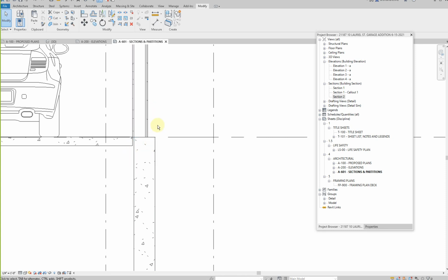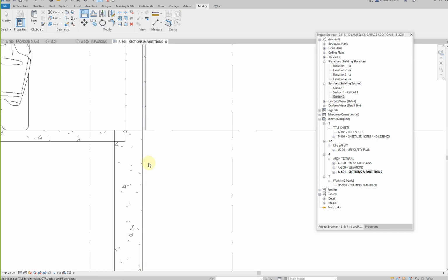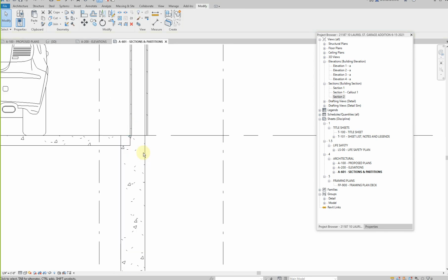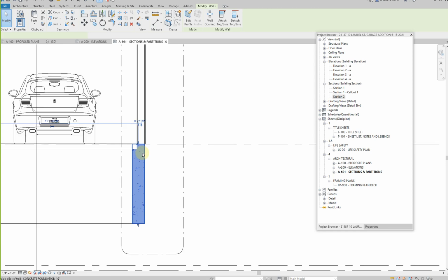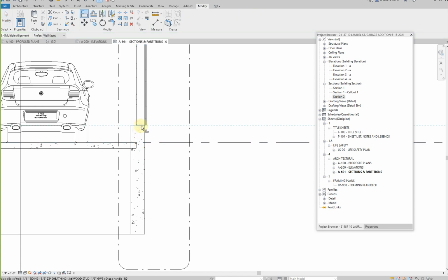If water was to hit this piece and ice, it would sit right in there and create a problem. You never want to have your foundation overhanging outside like that. They actually go inside like that. You see, that's how they go. The other thing is, you never want to have the foundations aligned with the grade. This has to actually go a little higher. How much higher? Well, I'll tell you later. But for now, let's just expose it a little bit like that.